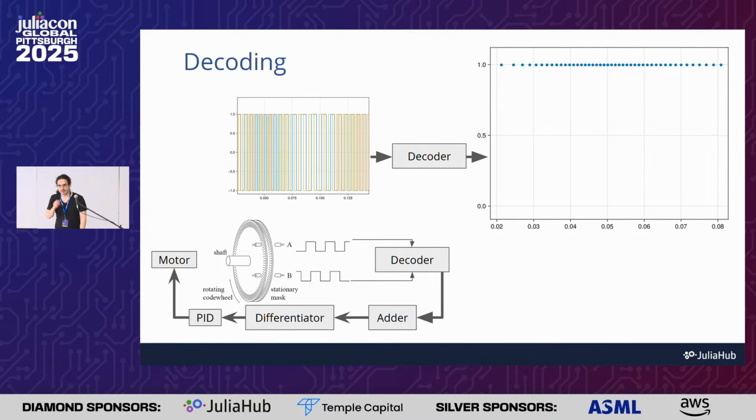As an example of this, it takes in this sequence of events where we get the chopper signal coming in, and then it turns this into a 1, a 0, or a -1 that happens on the clock of the 2 encoder inputs. Here, the value is all 1, which is why I've plotted it using points instead of lines. The line plot version wouldn't be very interesting. Here, the simple presence or absence of a point is what's interesting. The times that they're happening at is really what's encoding the information about how fast the wheel is spinning.